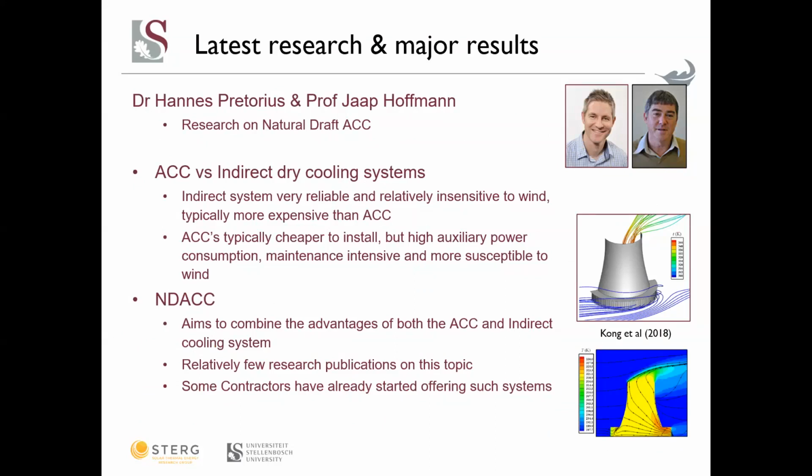And ACCs are typically cheaper to install, but have high auxiliary power consumption, are maintenance intensive, and more susceptible to wind. So we're looking at the natural draft ACC with the aim to combine the advantages of both the ACC and the indirect dry cooling system. There have been relatively few research publications on this topic, although some contractors have already started offering such systems.